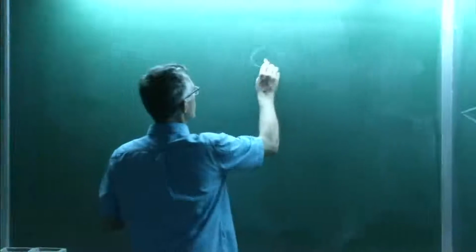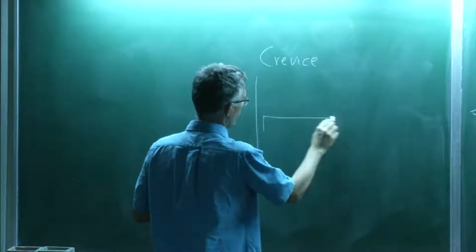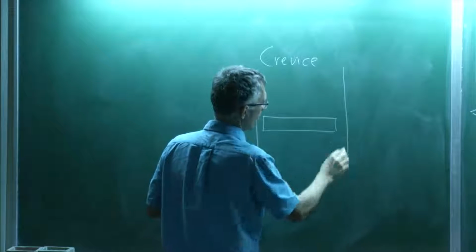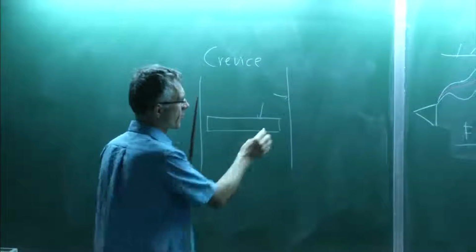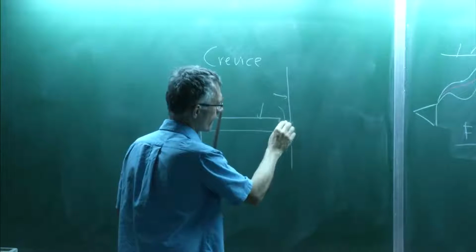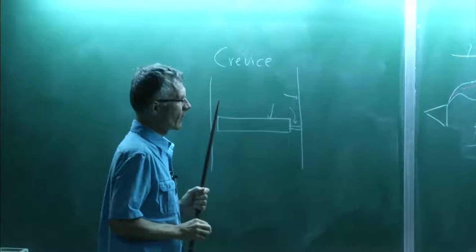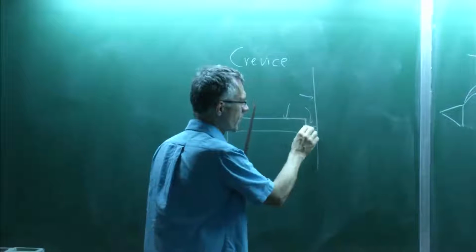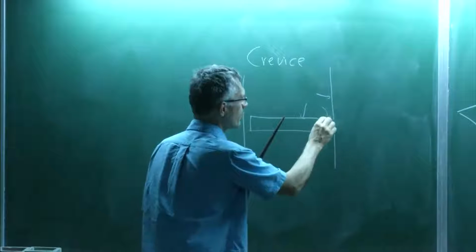There's a specific example of that which is a little bit different: crevices in an engine. In an engine, you have flame-wall interaction here and there, but there's a place where flame-wall interaction is extremely strong. It's here. Of course, the flame cannot go through, and this is a place fully surrounded by walls, so the flame usually stops there.